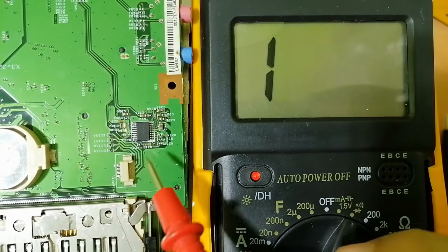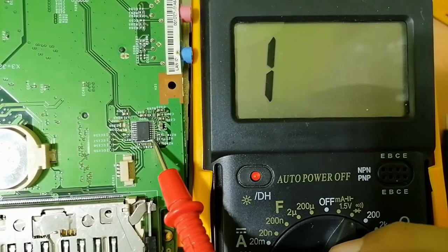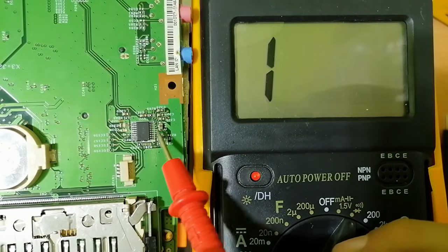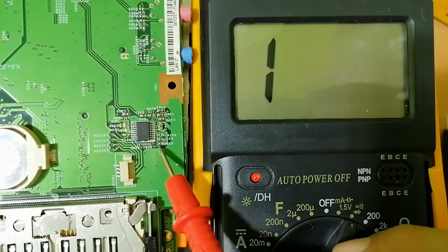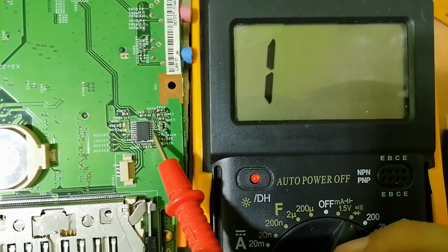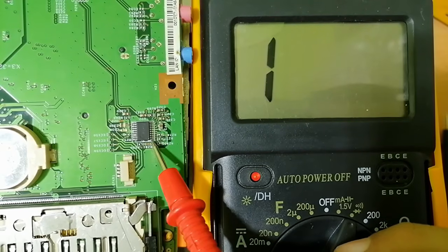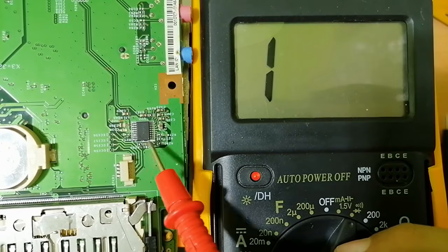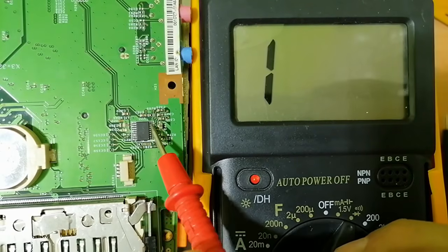Let's assume, for example, that this is the input of the IC, in this pin. The output, for example, is 3.3 volt. To get 3.3 volt here, the IC first should receive the input signals, including the input voltage, the VCC, for example, 5 volt. If 5 volt is missing here, it's impossible. We cannot get the output. So when you didn't get the output, it doesn't mean the IC is bad, is failed. No, you should go back and check all inputs.